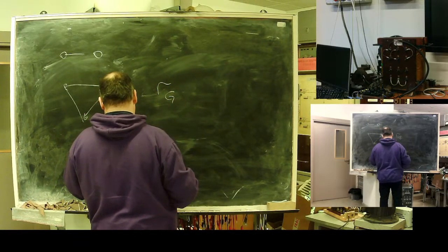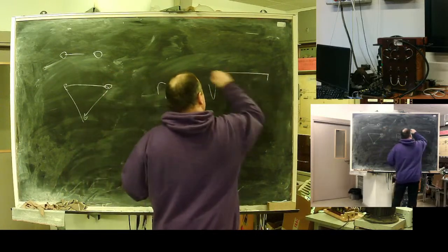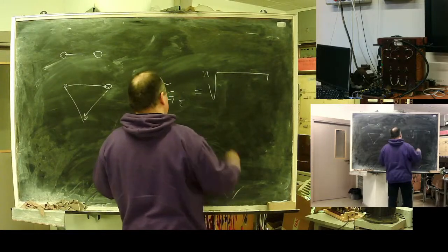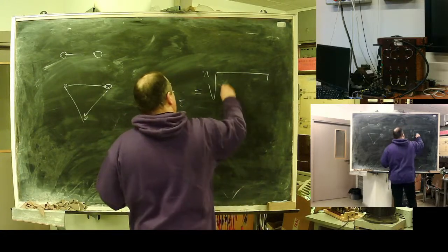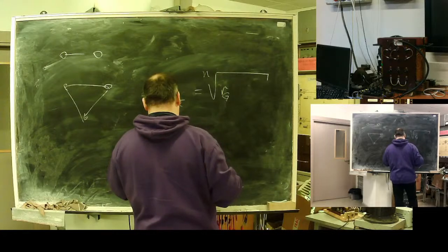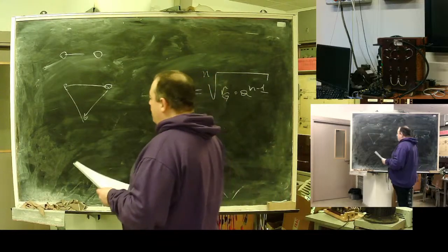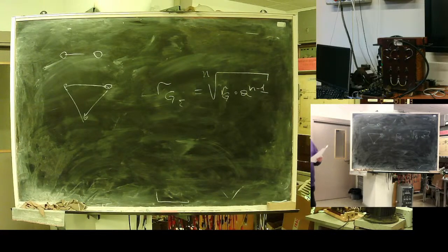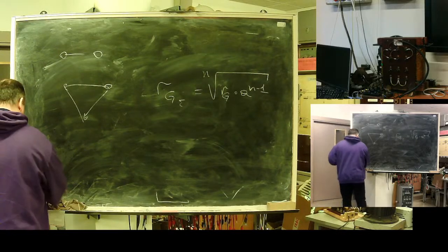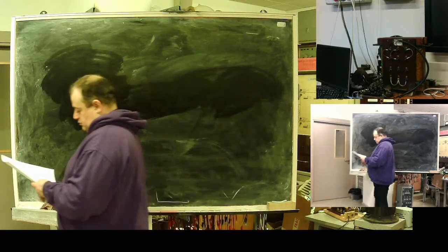In such case, GMR for the whole system summary will be the n-th root, where n is the number of wires in split, of GMR for one wire multiplied by GMR, distance between wires. Okay. Let's go forward.